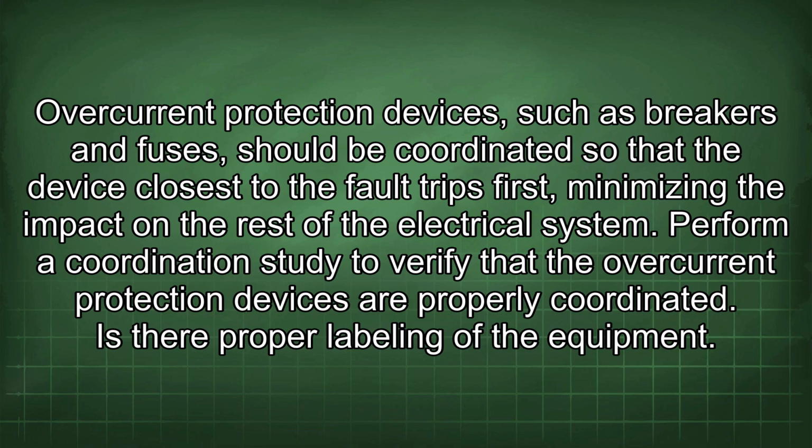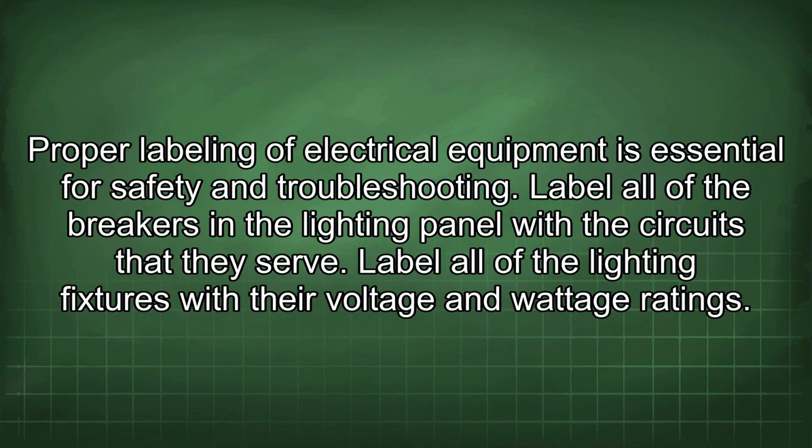Perform a coordination study to verify that the overcurrent protection devices are properly coordinated. Is there proper labeling of the equipment? Proper labeling of electrical equipment is essential for safety and troubleshooting. Label all of the breakers in the lighting panel with the circuits that they serve.